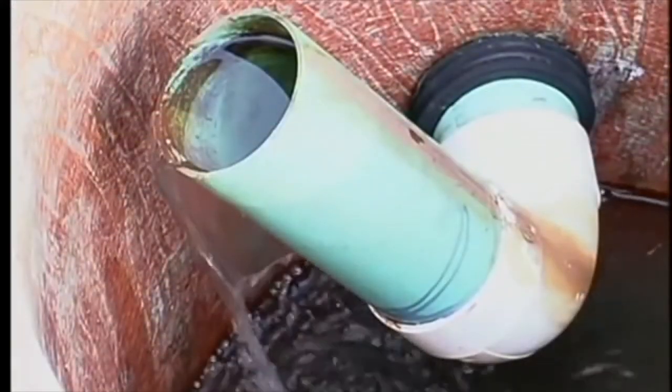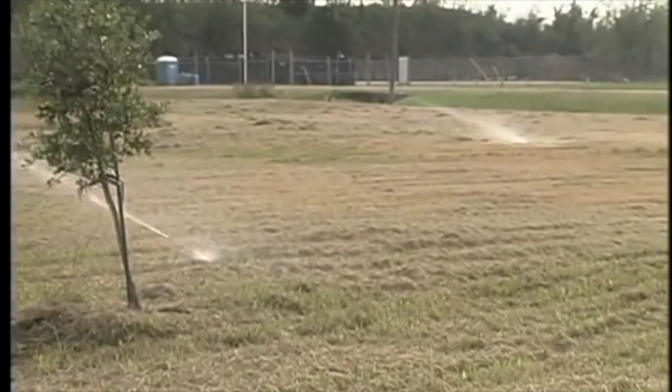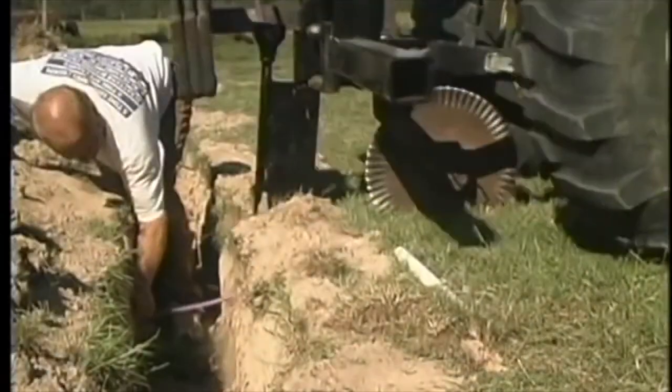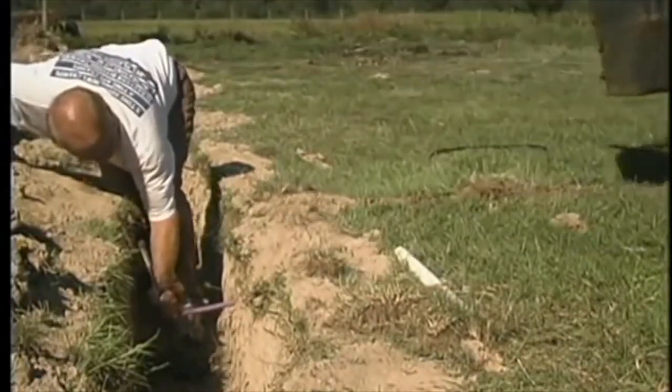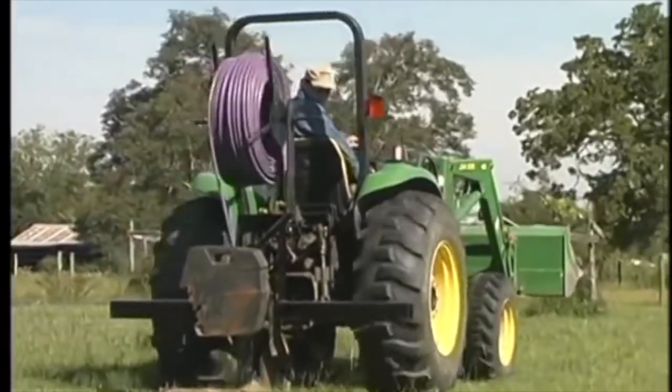Pre-treatment systems remove a sufficient quantity of the contaminants so the soil can provide final treatment and reuse of the wastewater. When selecting the pre-treatment system, you must determine the treatment capability of the soils at the site, whether you wish to reuse the water to irrigate your landscape, and the type of land application system. Each land application system requires a particular quality of effluent for it to function properly, and generally, reusing wastewater requires the highest quality of water.